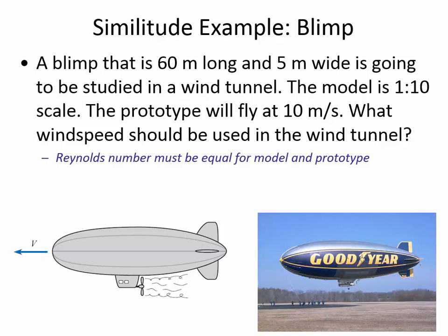And so you have to have more wind going into that smaller scale model in order to have the same ratio of forces. So, from just a logical, physical perspective, trying to understand and accept the numerical side of things, I think that may help to explain it. Any questions about the idea of dynamic similitude?